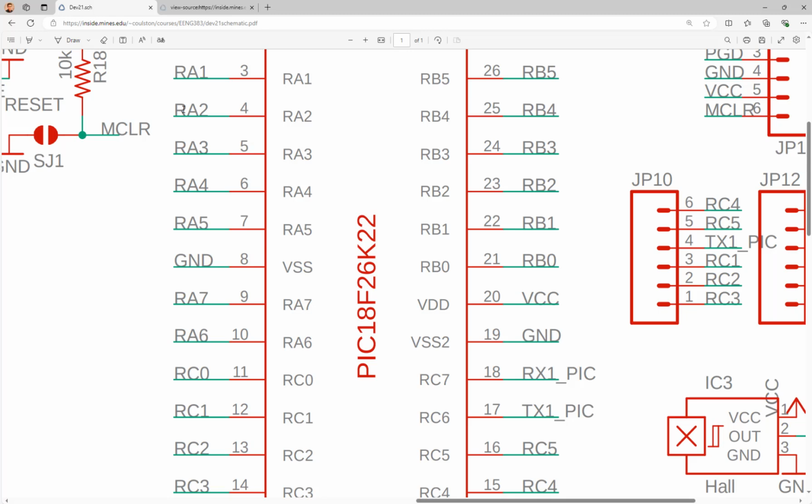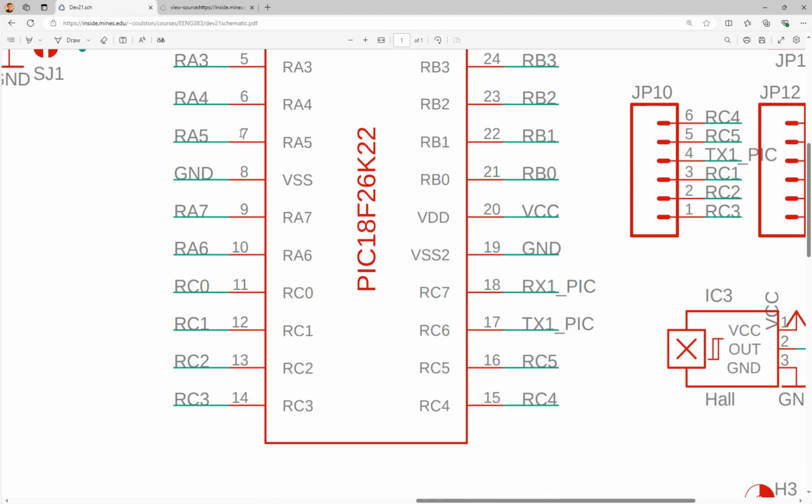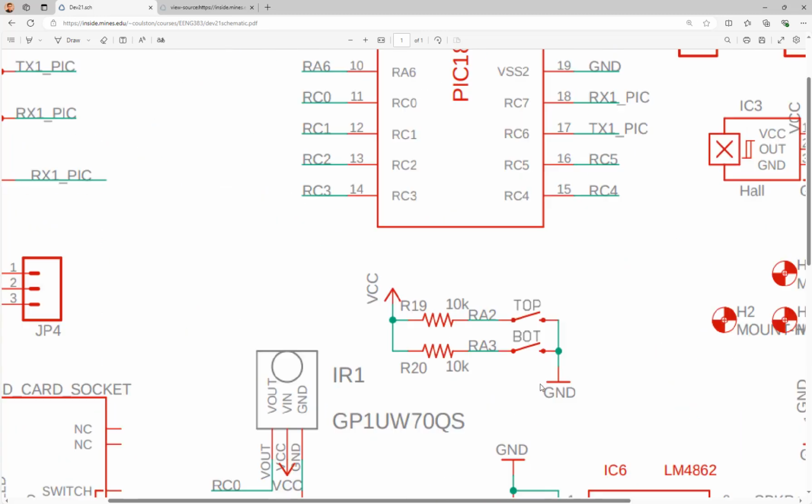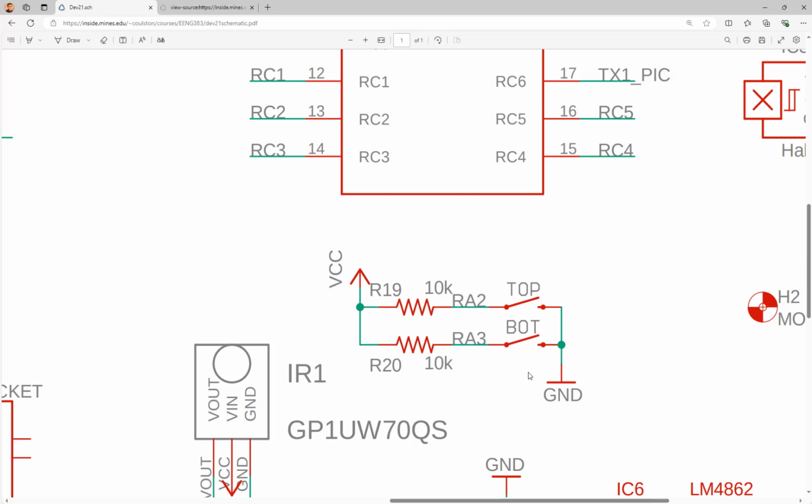You right click and rename it. It's going to ask, hey, are you sure you want to short this one to somewhere else? Just click yes. Then it's going to electrically connect the two pins together without a physical wire. You know what I mean? If you convert this schematic to a PCB, you'll see a physical trace connecting these two pins. But for the schematic it doesn't matter. It's just a picture showing all the circuits. It's not a physical layout.